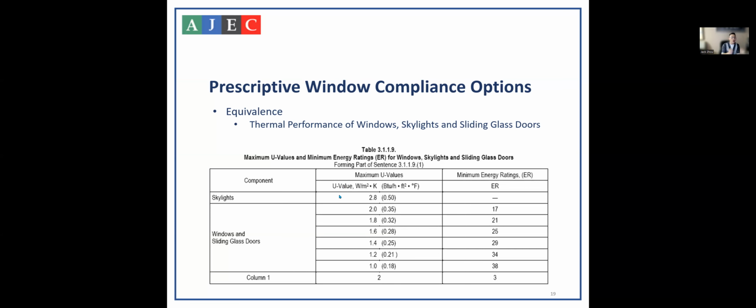So when you talk to the window manufacturer, you have to specify that you're looking for the overall performance, not just center of glass, because many times I have experienced that salespeople will give you the center of glass value only, which is a very, very efficient number. You think that it's compliant, and then when they ship you the product, the overall performance is actually not at 1.6 or 1.4, it's actually at 2. Then you just screw yourself over, because the whole window assembly is not compliant. So it's very important that you ask for the overall performance of the whole assembly, not just the glass.